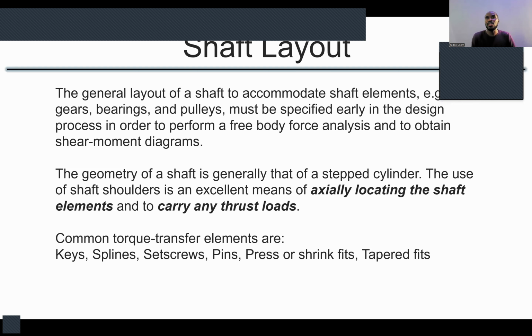So early on in your design stage, in the ideation stage, you should specify your general shaft layout. If this is my shaft, where will my gear sit? Where will my bearing sit? What should be the distance between my gear and my bearing? What should be the distance between my pulley and my bearing? And all of that, that's what we call shaft layout.